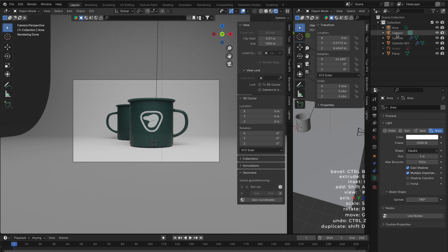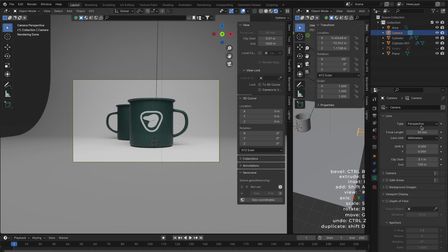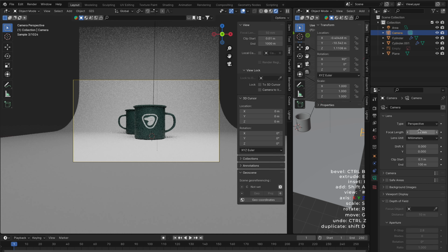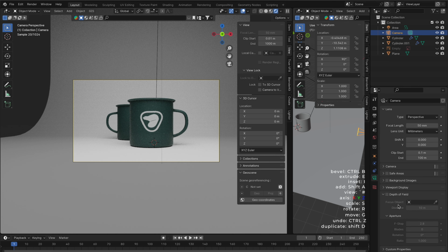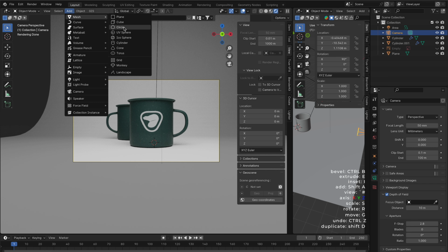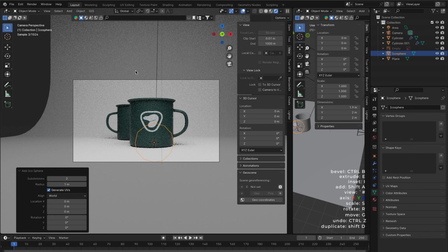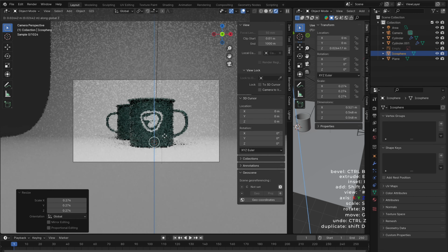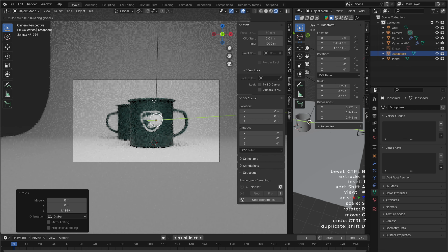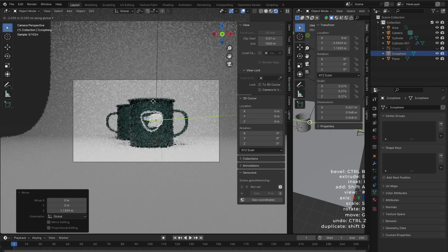One last thing I will show you though is the camera perspective here. So we can change the camera focal length if we wanted. We'll just leave it at 50. It's a good prime to have, but we will turn on depth of field. And what I'm gonna do is add in a mesh icosphere here. Doesn't matter, any mesh you want you can add in. I'm just gonna scale it down, raise it up, and then bring it forward. I'm basically lining it up with the beaver.